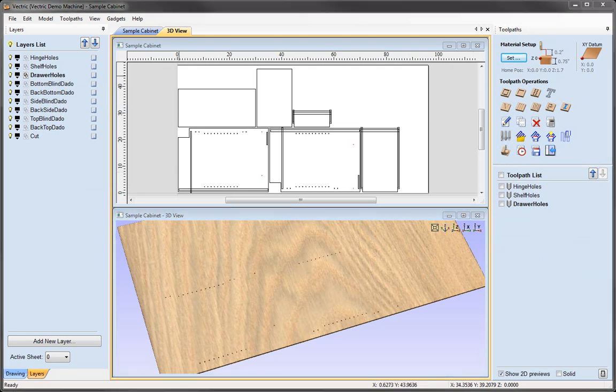Now you can see that we've calculated 3 different toolpaths, but in each one we've used exactly the same set of parameters. So in theory I could have calculated a single toolpath and just associated it with the vectors on all 3 of those layers using the vector selector. The main reason I haven't done that is to give myself more flexibility when using this template on future parts.